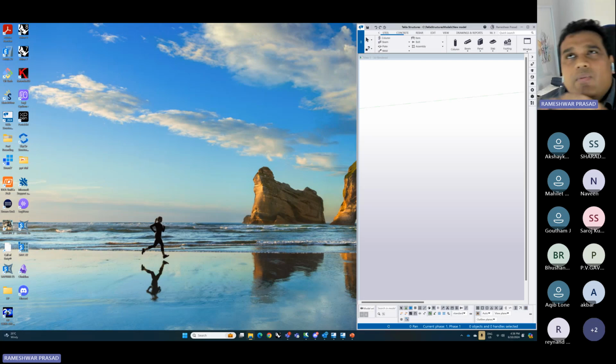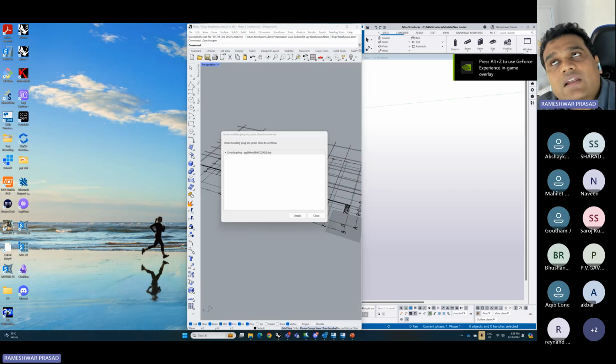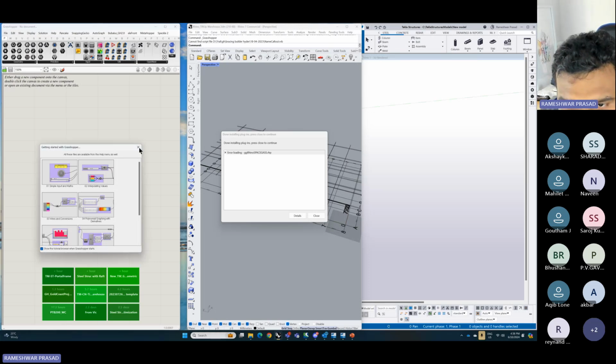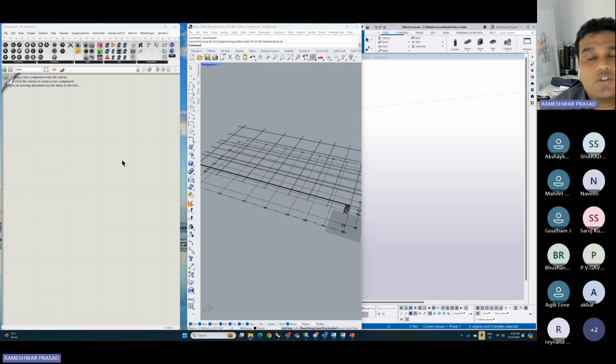So I'm currently using Rhino 7 because we started off making these components for Rhino 7. We are slowly migrating to Rhino 8 because that is the latest version. The difference is that the components need to be changed to .NET Core, .NET 8 if I remember correctly, whereas the older Rhino 7 works in .NET Framework. Rhino 8 also has a compatibility mode where you can use .NET Framework, but I think it is more robust to redevelop your Grasshopper components to adhere to .NET Core.